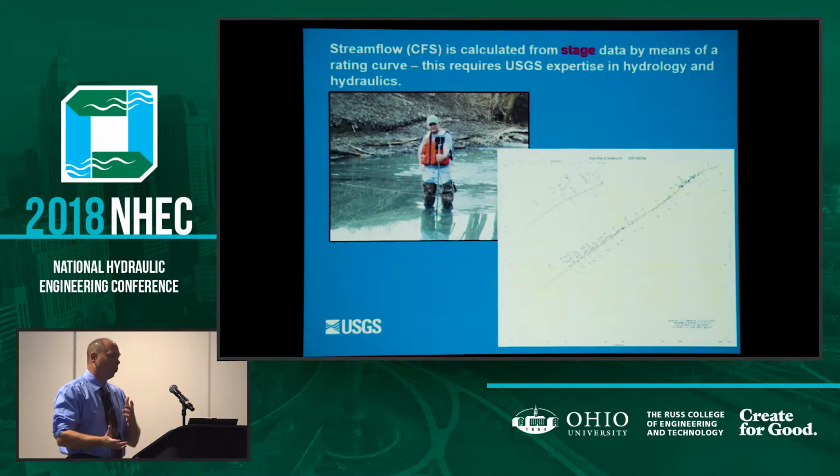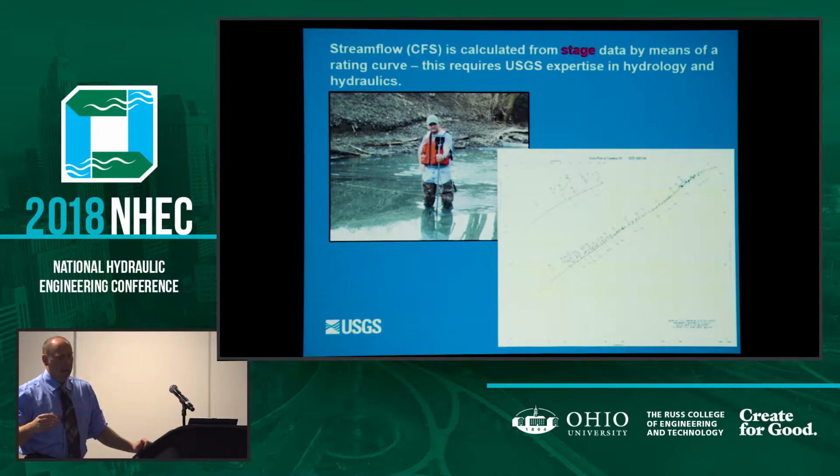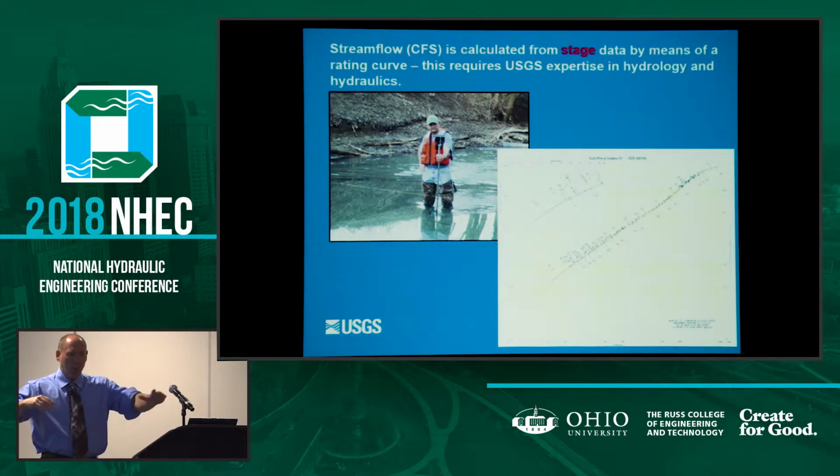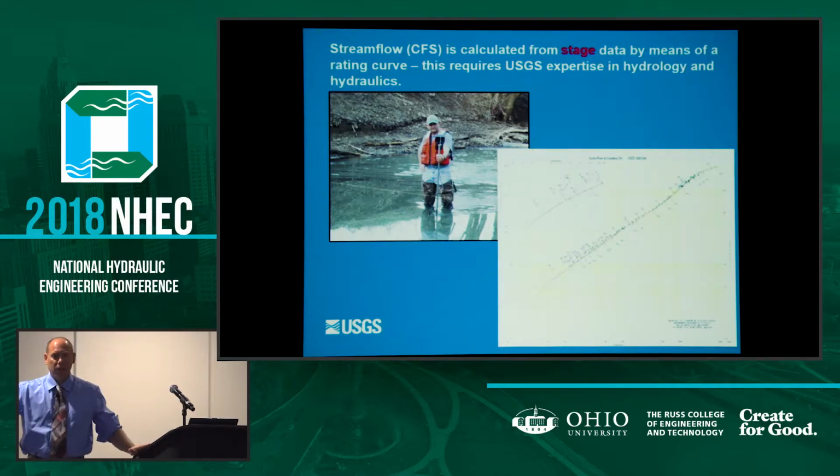Yes, we redraw ratings. Things happen in the channel. You can imagine if you had a river channel and all of a sudden you had a large tree fall into the stream, that tree would obviously collect debris. Your flow would not change, but your stage would be backed up from that tree. So in a sense, you would have the same flow, but you would have a higher stage.